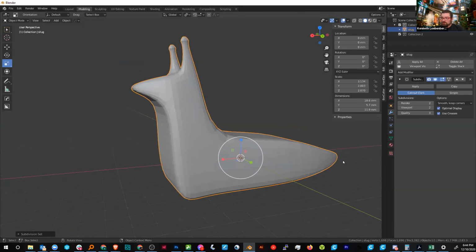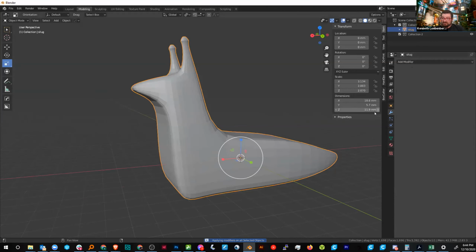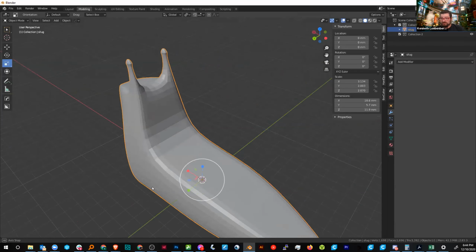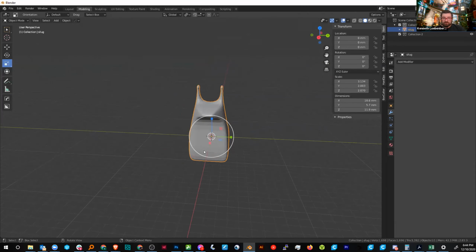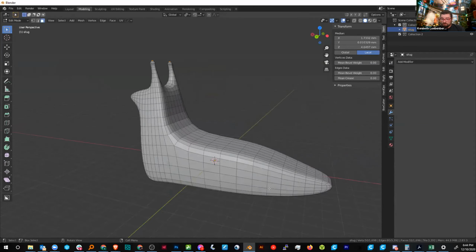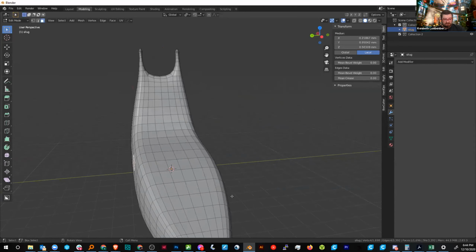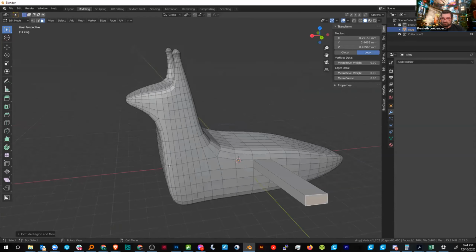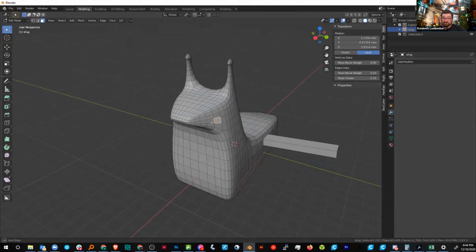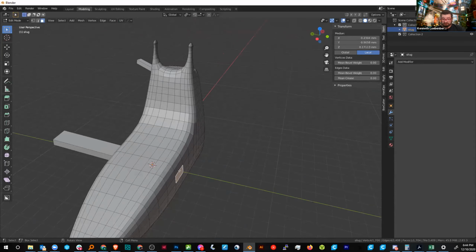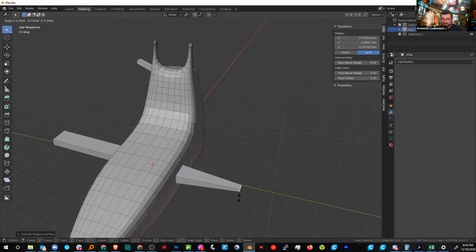And now we might want to sculpt that. Now we would probably have to apply that first. So if we apply that, now it's gone, and this is just permanent. It's just the way it is. So now if I go over to edit mode again, you can see, remember we had a couple squares? We have a lot of squares now. So each one of those squares is a face. And I can still hit extrude on any of these, and it will extrude them. It will just look funny, like I'm stabbing this thing. There we go.